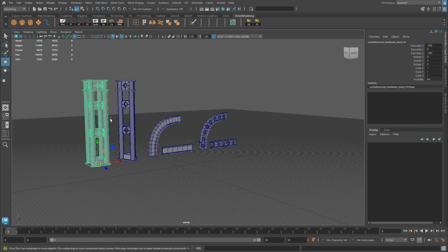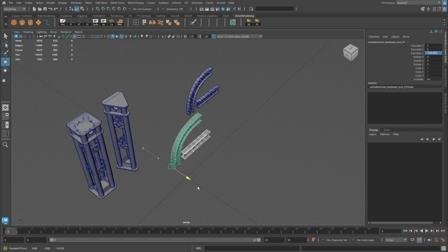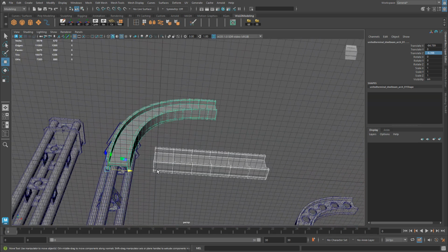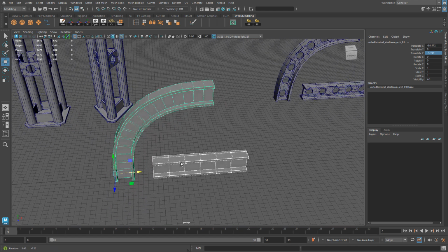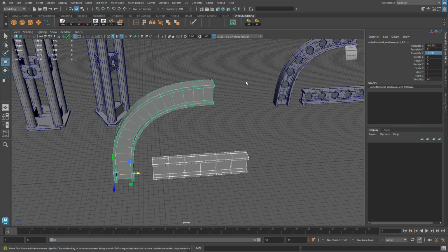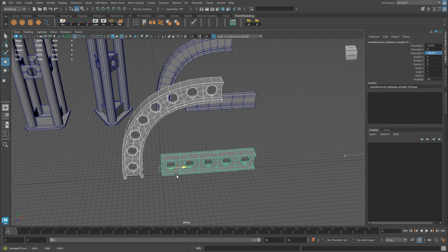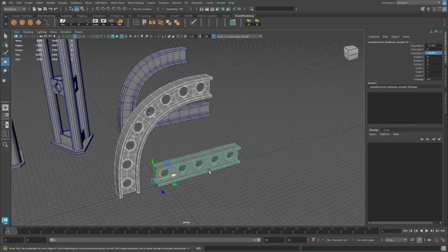I did the same thing for this one, world origin. Exported it as FBX. For these two, I just simply brought them into the world origin, like so, somewhere close enough. So their pivot point will be positioned at the world origin, so ignore this pivot point on this mesh. I simply placed them close enough to the world origin, and I exported them together. So when they are brought into Substance Painter, they will be one single mesh. And I did the same thing for this. I just simply took these two meshes, placed them right here, close to the world origin. On export, the pivot point will be at the world origin, and these two meshes will be combined as one. And we'll end up also bringing this one into Substance Painter, so they are together and we can see what we're texturing.